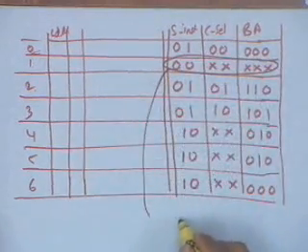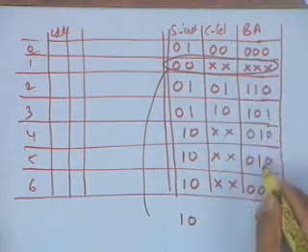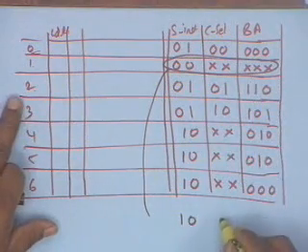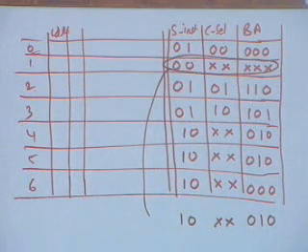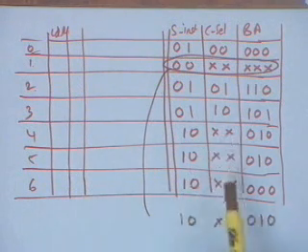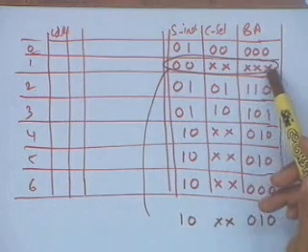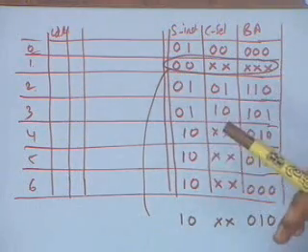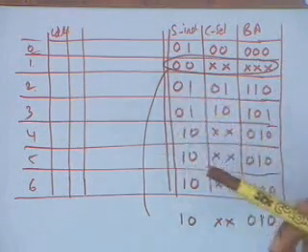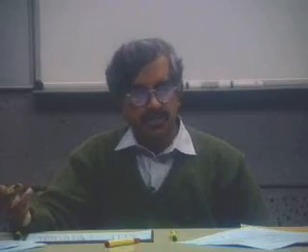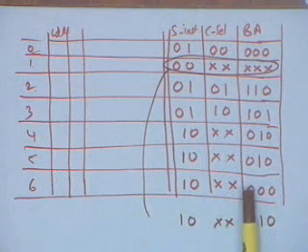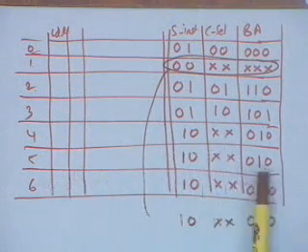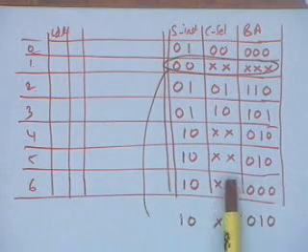what you can do is say it is 1, 0, and you can replace it by that. But the problem is, in this particular example it doesn't make much difference because there is only one place where don't care is coming. But if you have a large state machine and there are a lot of edges which correspond to just going to the next microinstruction, a lot of don't cares will help me in reducing the width of this microinstruction. I will come to that point.